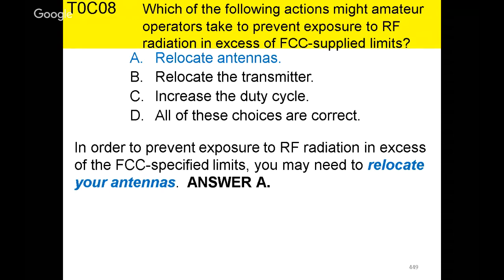I don't have to worry about it up here on the mountain. I know that I'm putting about 50 watts into my antenna from my radio, and my antenna has a 6.5 dB gain. So that's quite a bit of effective radiated power going out my antenna, way above what the FCC specified limits might be. But I'm not near anything. It's up on a 40-foot tower.